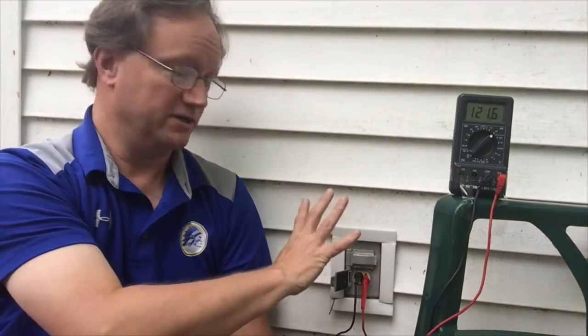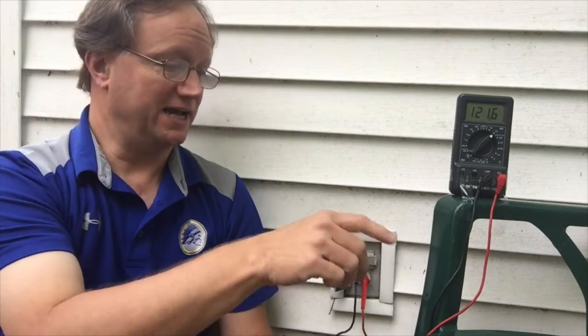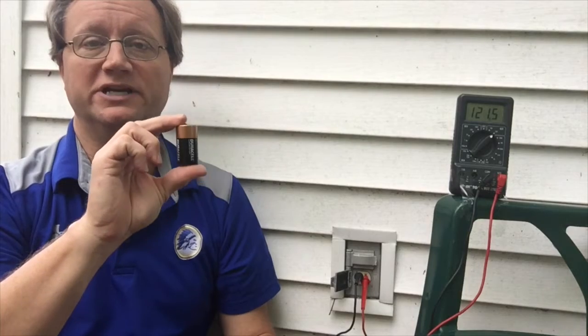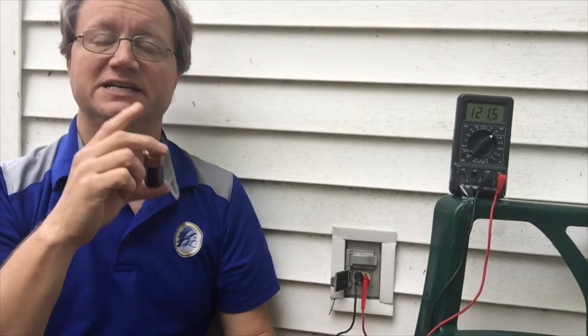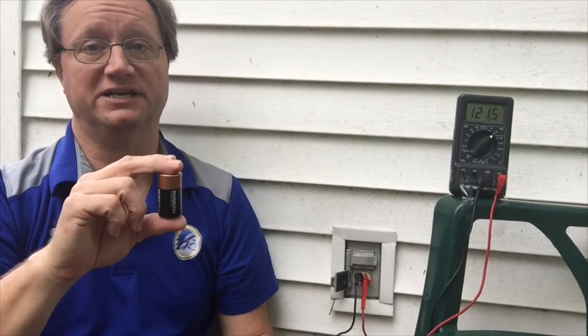So somewhere work was done on these charges to be able to give them energy, and when you hook up a battery or plug something into an outlet, those charges flow and do work on whatever is in the circuit. So kind of in summary, when you see a number in volts, what you need to think of is joules of energy per coulomb of charge, or joules of work that the flowing charges can do for each coulomb of charge that is made to flow.